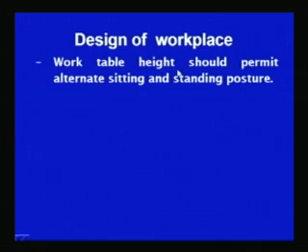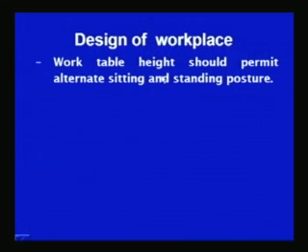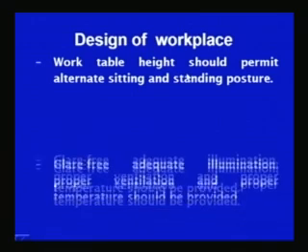Some other points related with the design of the workplace, like work table height should allow the alternate sitting and standing posture, so that the fatigue being caused by the work to the operator can be relieved with the alternate sitting and standing posture during the work. So, work table height should be such that it permits the use of alternate working in standing and sitting positions.